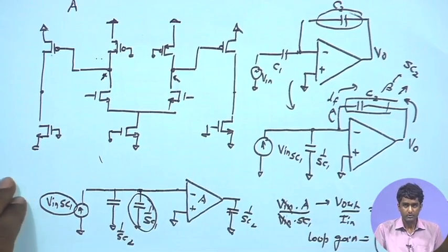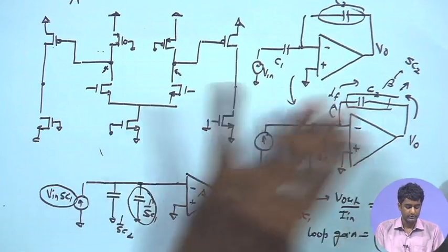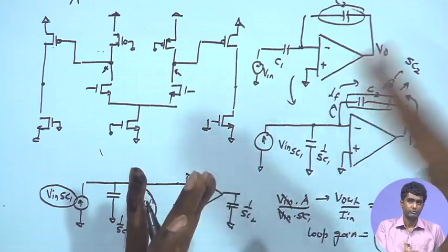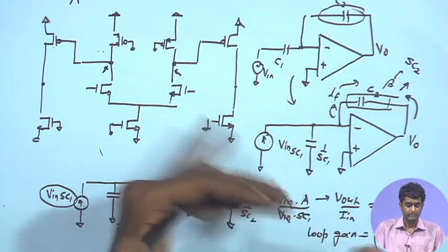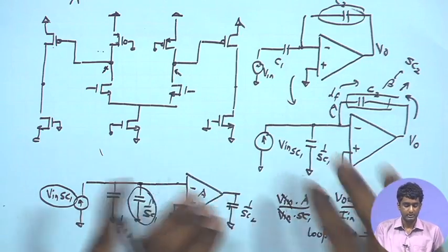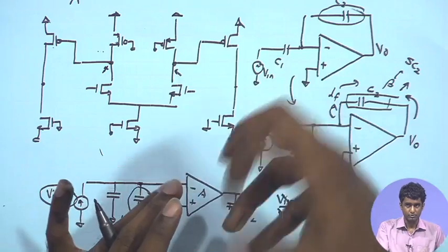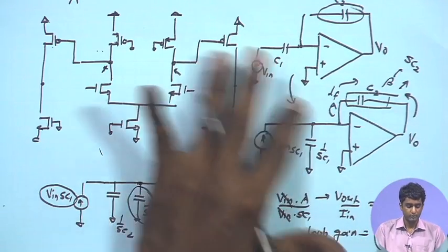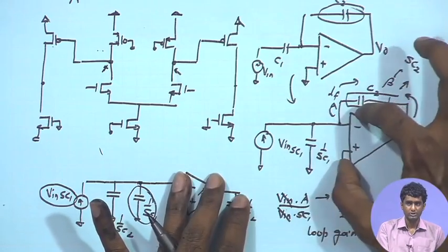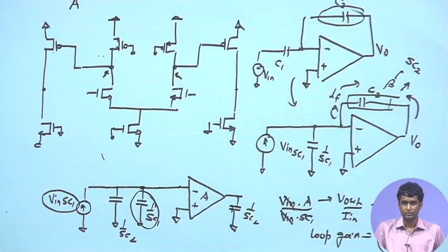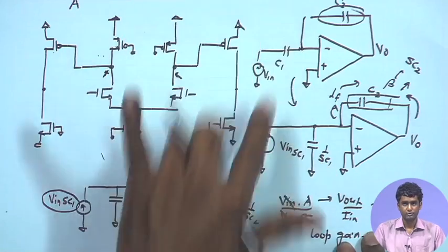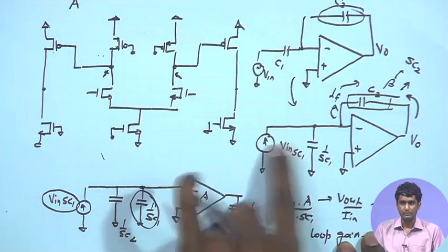And the only thing that we have to take note of is that we are using this amplifier overall as a voltage to voltage amplifier, but the feedback topology is a shunt. So, we are transforming the input source into an equivalent current source and then doing the rest of the analysis. After that, if you assume that this is a given source and this is the topology, from here this overall derivation should not be a problem. The only thing is the initial step involved in transforming this input signal as a voltage to an input signal as a current.